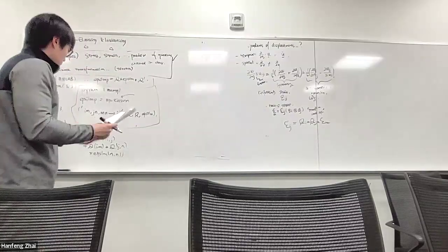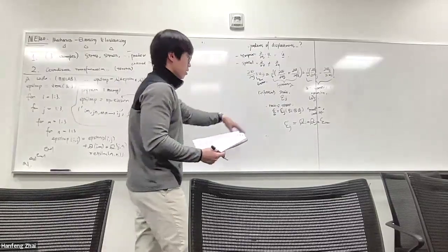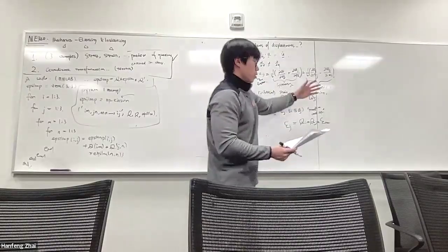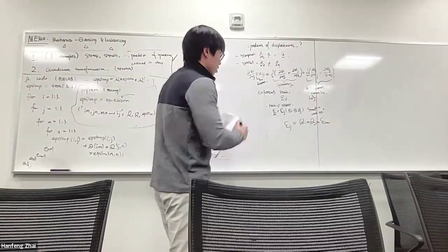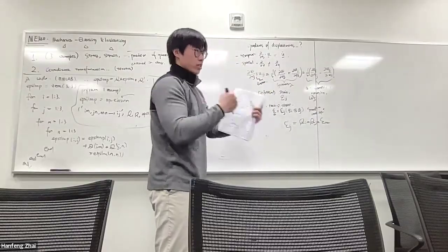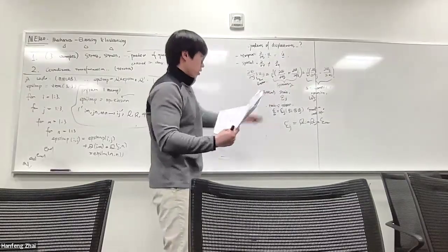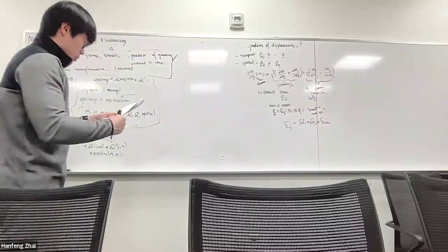Cool. So we already defined the strain tensor properly, and we know that by definition, the strain tensor is symmetric, and the rotation corresponds to the anti-symmetric part. Strain physically corresponds to stretching a body, which takes energy, so that's why it's symmetric. So by definition, strain is the symmetric part of the spatial gradient of displacement.